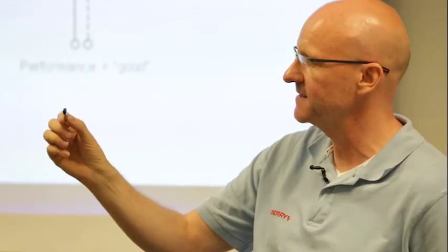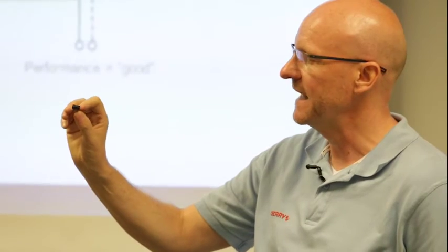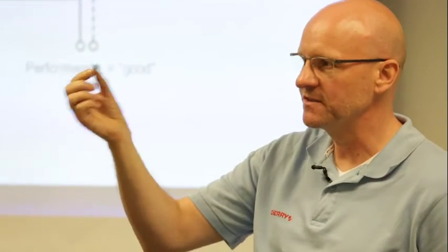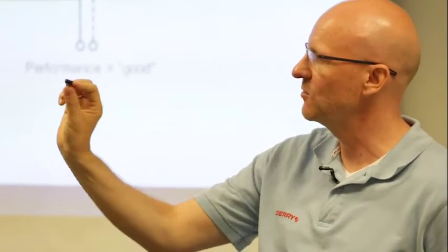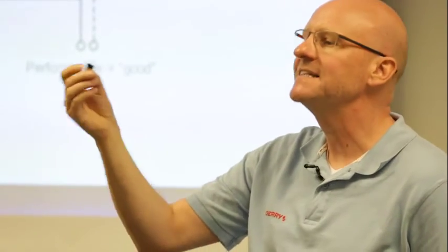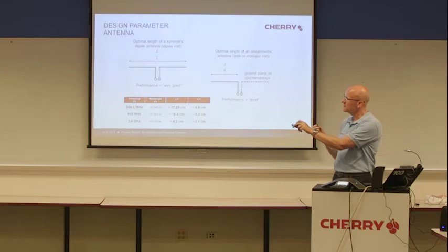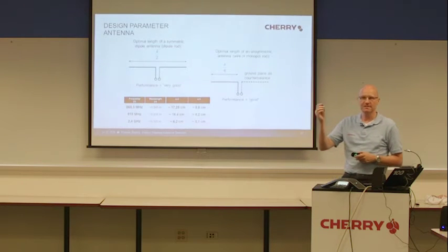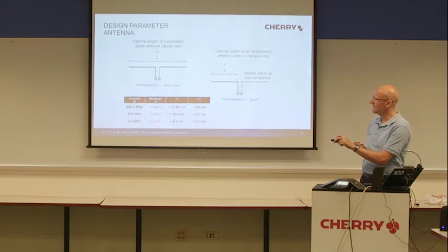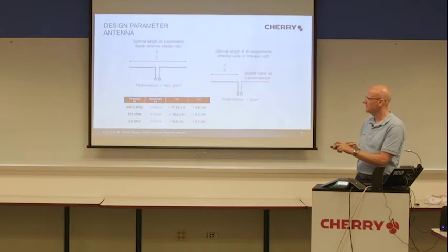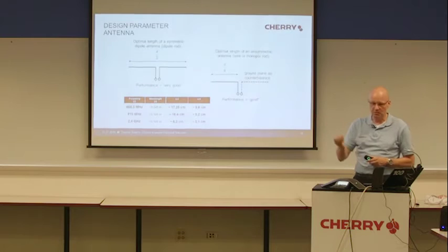These are chip antennas or SMD antennas placed directly on the SMD. The performance of a 2.4 gigahertz antenna on such a small receiver is much better than when you would use the 868 or 950 megahertz frequency. That is another advantage: the antenna design can be better adapted to small housings.